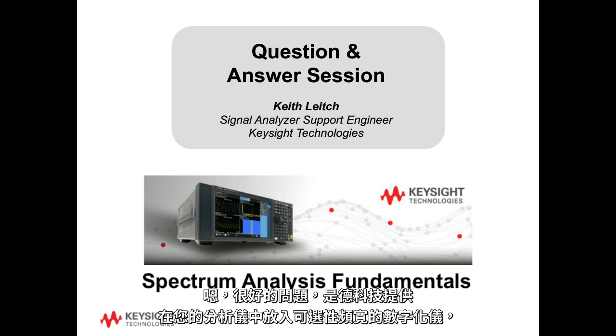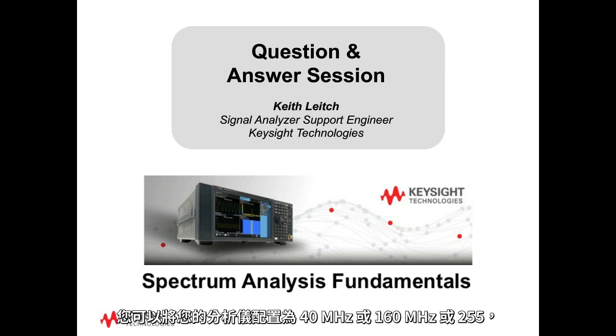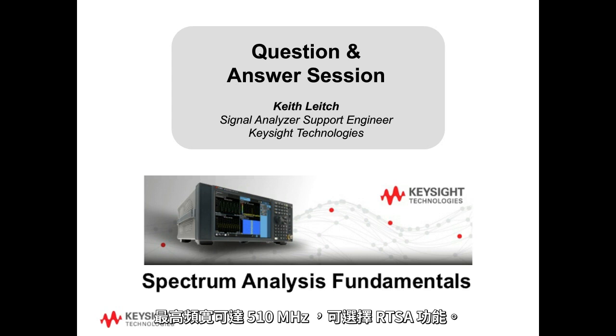Yeah, great question. So Keysight offers options to put a digitizer of optional bandwidth inside your analyzer, so you can configure your analyzer to be 40 megahertz or 160 megahertz or 255. We cover up to 510 megahertz of bandwidth with the RTSA feature as an option.